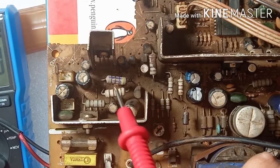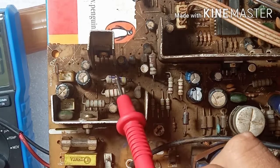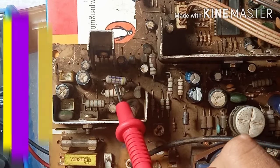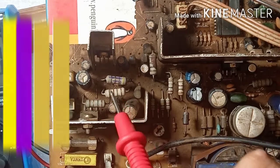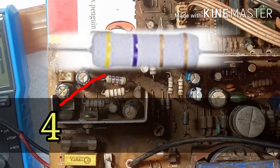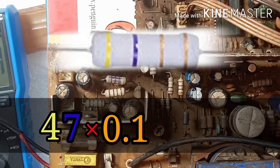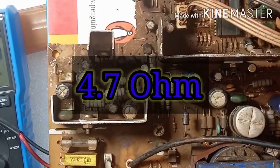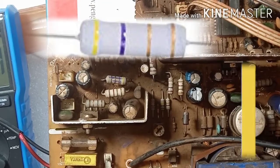So this is the resistor in focus, so I want to read it. We have yellow, violet, gold, gold. When interpreted, yellow equals 4 as the first significant value, violet equals 7 as the second significant value, gold as multiplier equals 0.1. That means 47 times 0.1 equals 4.7 ohms.